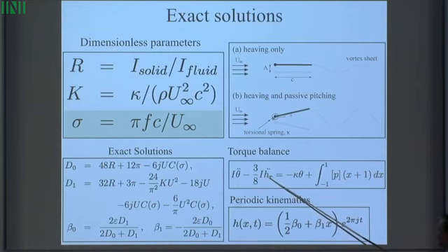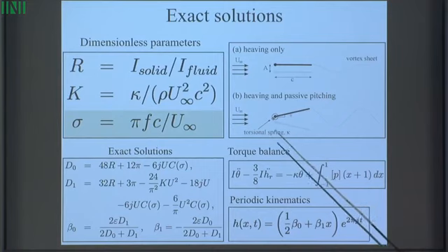That's okay. This is just an angular acceleration term that comes from taking the reference frame of the wing that's moving up and down. That's all that is. Okay, so using Wu's theory, combining it with this torque balance allows me to solve explicitly for these coefficients. So I impose the overall driving amplitude of the wing, and then I solve for its emergent pitching motion.